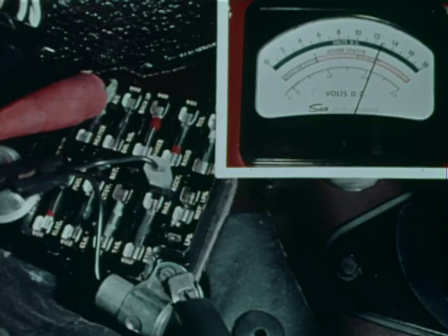So next, check the system voltage by connecting the voltmeter between ground and the ground side of the AC fuse. If the system voltage is below 12.8 volts, you will have to troubleshoot the charging system. In this case, proper system voltage is present, so you will have to check each component in the clutch circuit until you find the one causing the low voltage at the clutch.